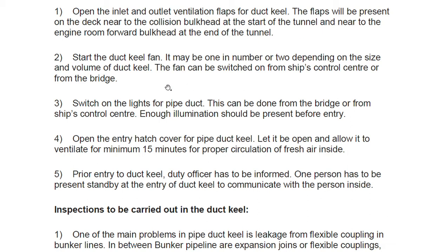Otherwise, the entry procedure for an enclosed space, because it will be treated as an enclosed space, will always remain the same. We need to carry out the risk assessment. We need to have a checklist. Start the duct keel fan. It may be one in number or two depending on the size and volume of the duct keel. The fan can be switched on from the ship's control center or from the bridge.